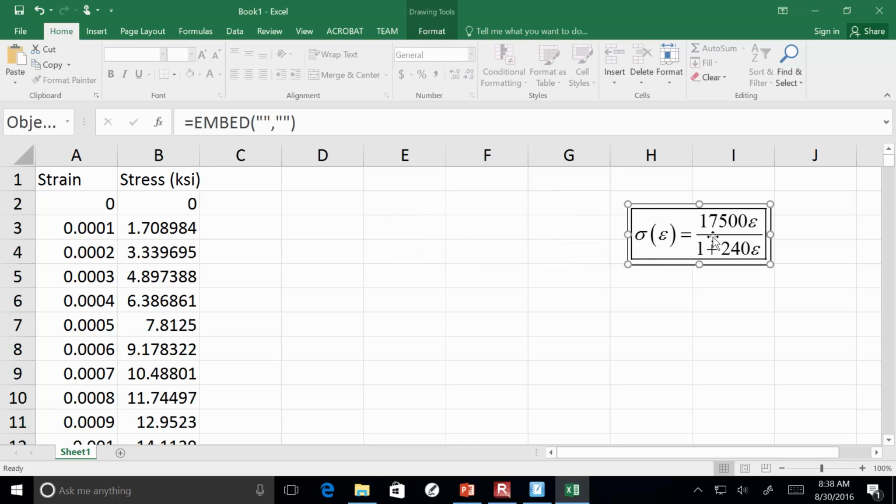Okay. So now we've got our stress strain data laid out. This is our strain. What are the units for strain? Anybody remember? It's a trick question. There are no units. Because it's change in length over original length, so it's inches per inch or millimeters per millimeter. So strain's unitless, and we're saying the stress is in KSI. For the purpose of what we're doing, it doesn't terribly matter, just as long as you're labeling it.